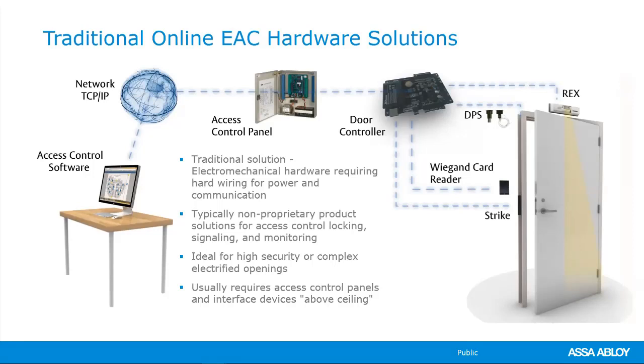And from there, we can narrow down even deeper into a second or third floor where we're going to have a door controller. From there, that's going to control a door. Each door is going to have a card reader right there on the wall, and it's going to typically be a multi-class reader, able to read any credential that you have at your facility. To secure that door, you're going to have an electric strike in the frame of the door, or if they core the door, they're going to have what's called electrified hardware, where wires are actually running through the door and the lock is powered.